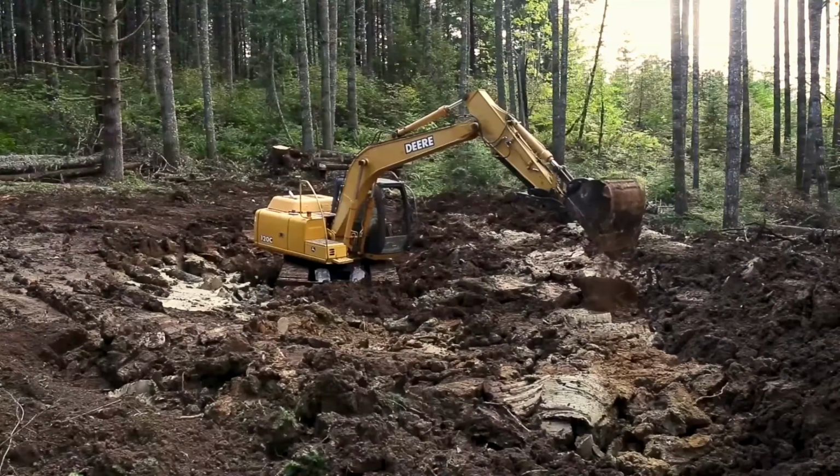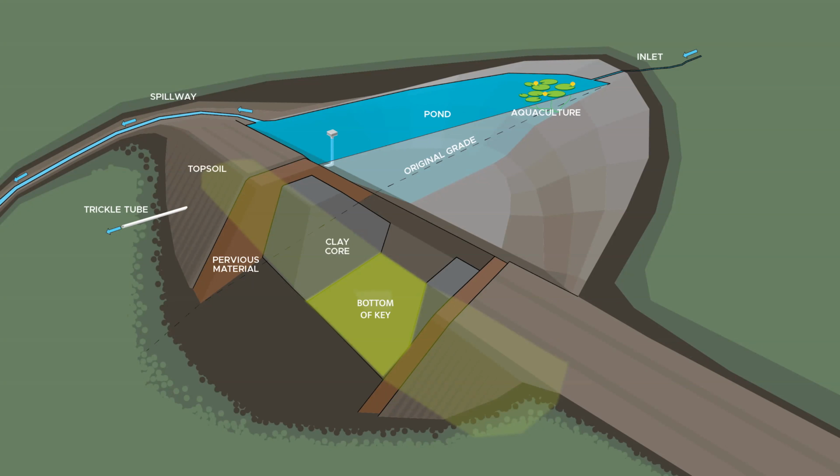As we make that excavation, we want to be careful, first of all, not to scratch and break up the dirt, the clay material at the bottom point where the dam will anchor into, because that can create a weakness point. But we can go to the outside edges of the dam where it's going to key into the side of the valley and create notches with the bucket, the teeth of the excavator, for it to get packed and keyed into on both sides.